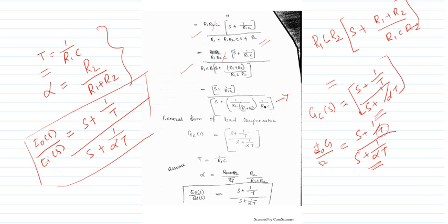And the lead compensator is also called a high pass filter, and the advantages of this lead compensator are increasing bandwidth, improving speed of response, reducing the amount of oscillation, and reduced overshoot. So finally I can make the particular system stable. That means this is my steady state line. If I draw my response going like this, then this is your oscillation, then overshoot and the steady state, right?